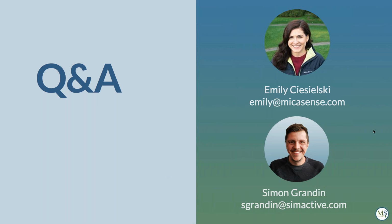Great, thank you. Let me see if we have more questions or if we have already answered them all. Okay, can you generate and display contours from the digital surface model file in Correlator3D? Yes. So you can either import your own contour lines, or you can select the model that you want. If you want to do it on the DSM or on the DTM, we have a tool to calculate contour lines directly in Correlator3D that will be saved into shapefile.